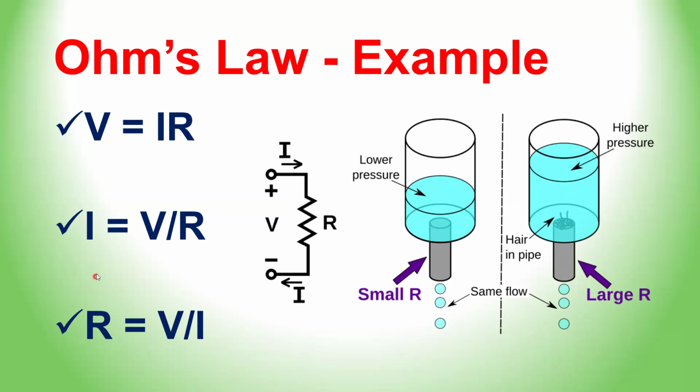So there are three primary equations by which we relate and understand Ohm's law, linking voltage, current and resistance to each other. The first formula is V equals I times R, that is, voltage is equal to current multiplied by resistance. In the second case, you can write I is equal to V over R. So you are taking the R from the right-hand side into the denominator on the left-hand side. So I is equal to V over R. That's what I have written here.